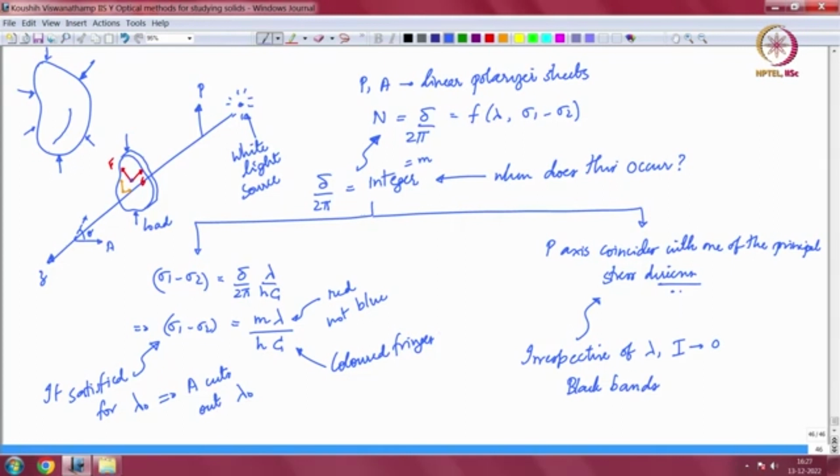Okay. There are names for this. The first one is called an isochromatic. Again the name is indicative, chromatic comes from the fact that it depends on the color or the wavelength, and the second is called an isoclinic. Okay, clinic comes, well, not from a doctor's clinic, it comes from inclination. So, this is basically constant theta direction. So, remember in the figure I have denoted this direction theta, which denotes the orientation of one of the principal axis with respect to the analyzer axis. It does not matter, pi by 2 minus that will be with respect to the polarizer axis, but at least one of those directions coincides with this, and so you get isoclinics here.